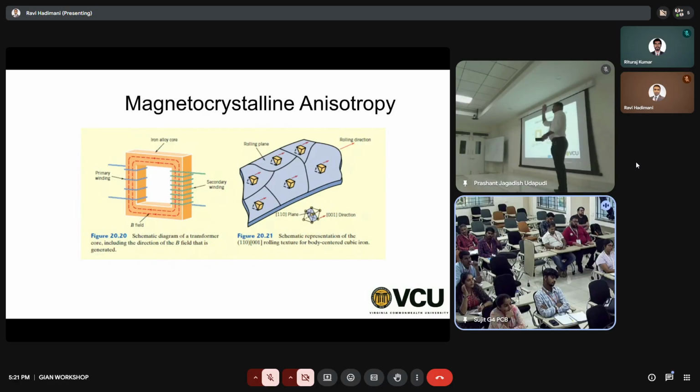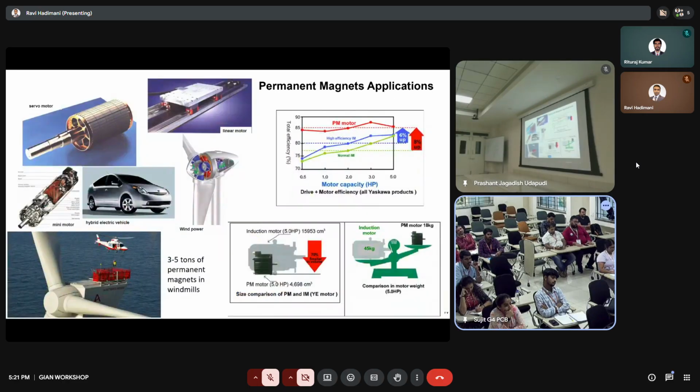Now all the grains that are formed have their direction oriented to the applied magnetic field, which means you control the lattice directions of all the crystals or all the grains in one direction. You did not get a single crystal, but you made all grains orient in one direction, right? So that is called magnetic annealing, which is a process that is used to align the grains.